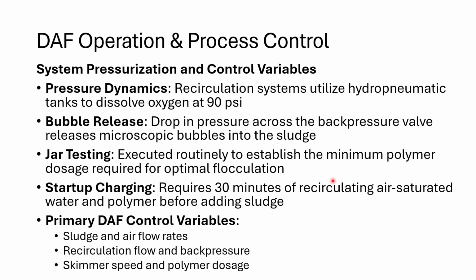That's going to form those bubbles, and they're really small bubbles when they're coming out into our process. The idea here is not to break up the sludge flock, but they're like micro bubbles, if you will, so that they're going to take that flock up to the top.